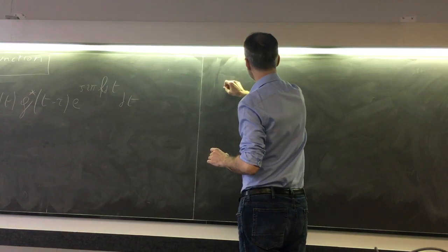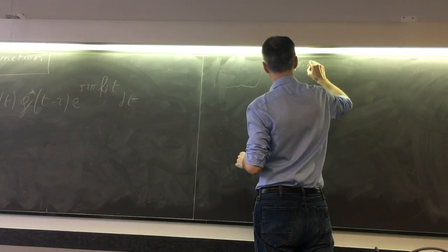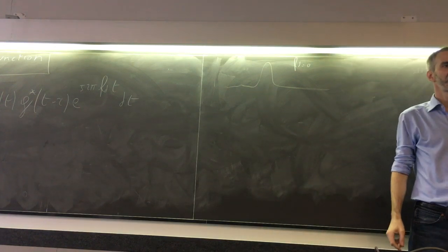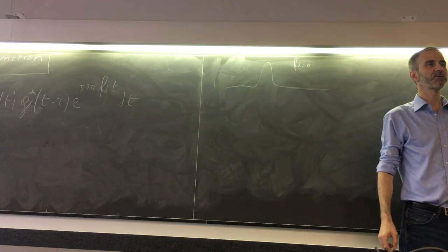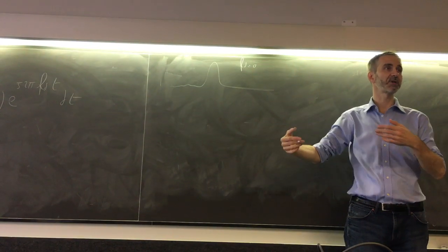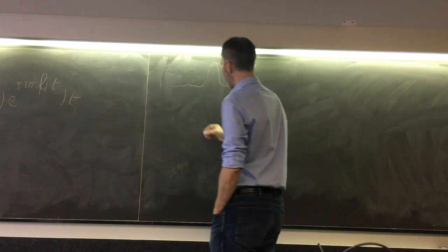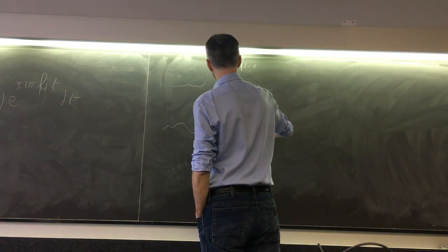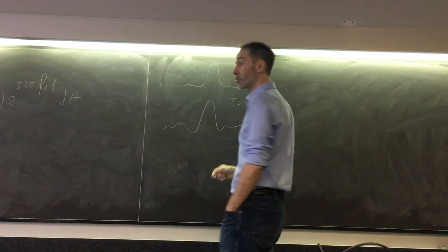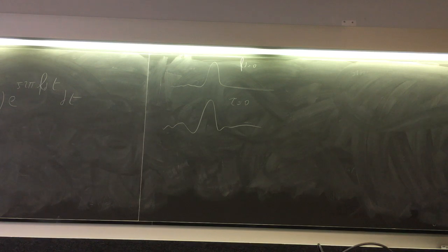In the section where fd is 0, which means you know the true Doppler frequency of the target, you get this peak, so you can detect the target's range. In the section where tau is 0, so you know the true distance of the target from the radar, you can estimate its speed.